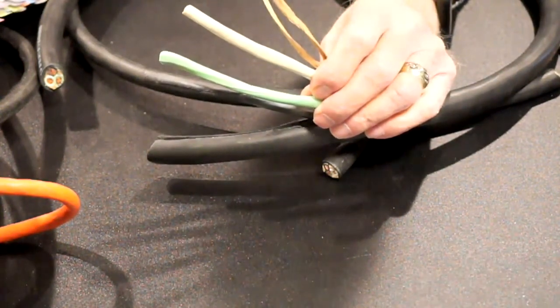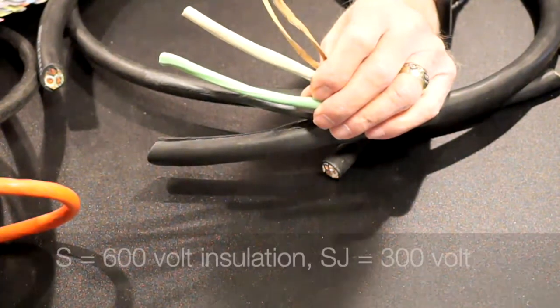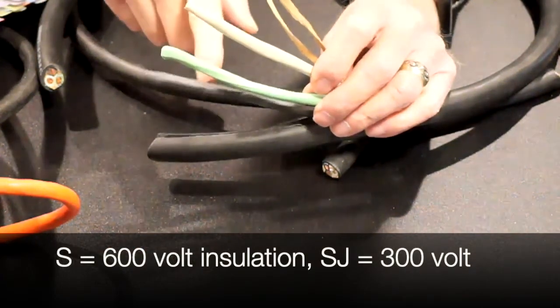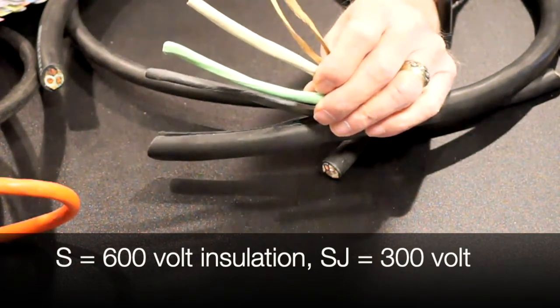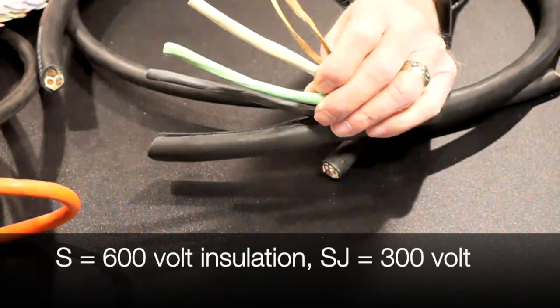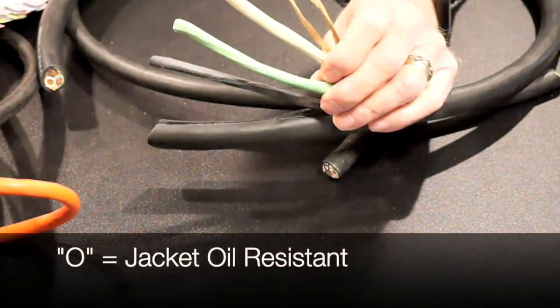Okay, so if it has the S, SOOW, the S indicates that the insulation itself is rated for 600 volts. If it was a junior hard service cord, SJ, then the insulation itself would be rated for 300 volts. The SOOW, so the S tells me that the insulation is rated for 600 volts.